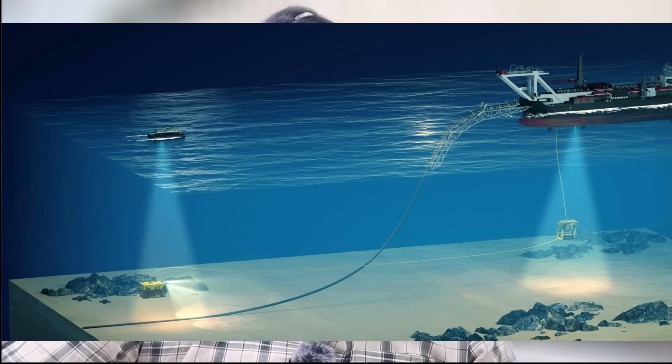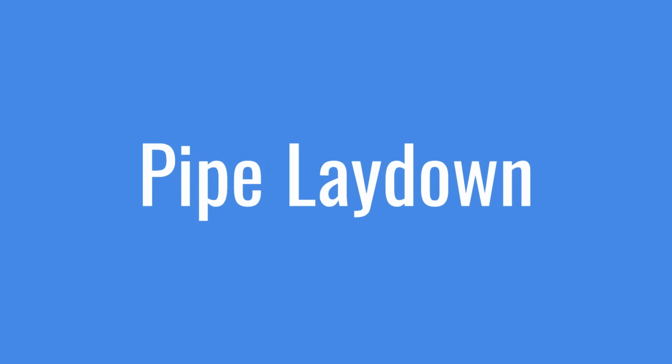So you must get an approved touchdown distance copy from the field engineer. Nowadays all the pipelay barges use ROV, which is very useful to know the actual touchdown point, and you can compare it with the theoretical touchdown point and correct it if necessary. Now laying down of the pipe is a complex operation and needs a little bit of calculations.